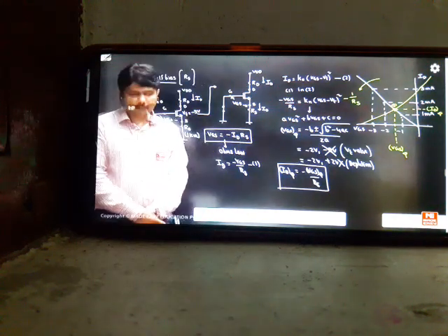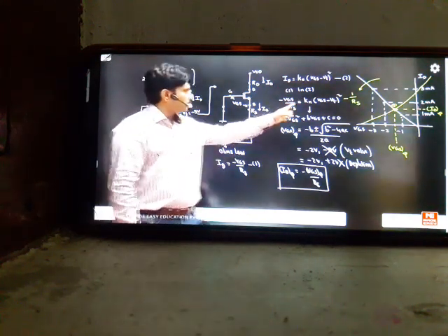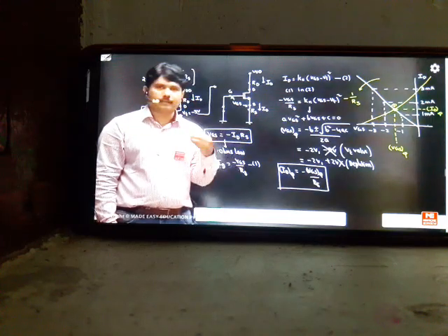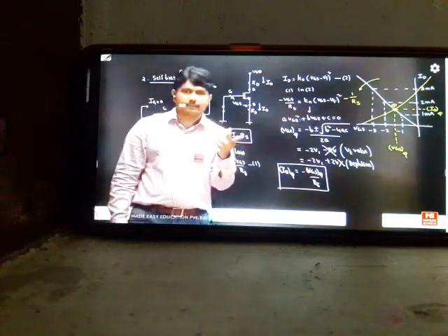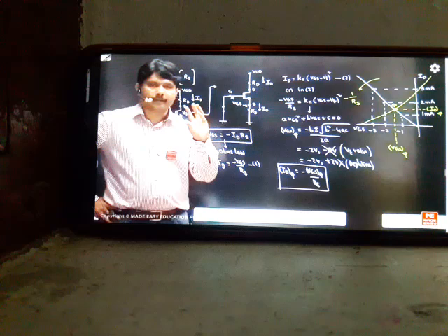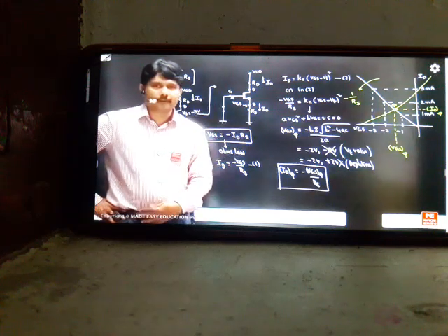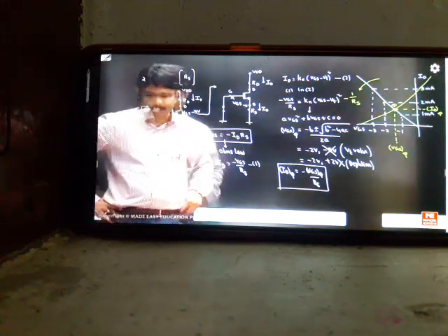Yes, Pandit. All the formulas are the same here. This formula is the same for everything. Whether you take enhancement or depletion, whatever you take, the only thing is the VGS values will change. VGS value is negative for depletion type. VGS value becomes positive for enhancement type. Nothing more than that. The values inside change, but the formula will be the same.